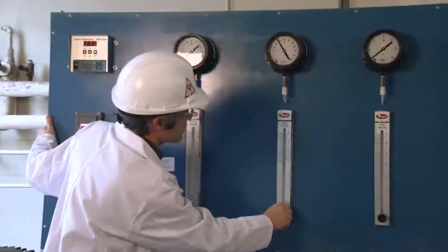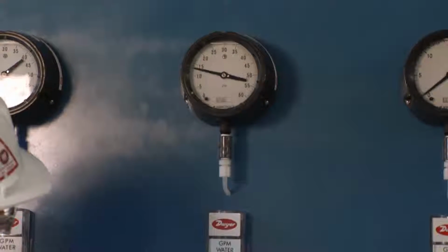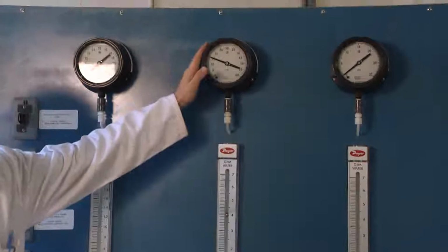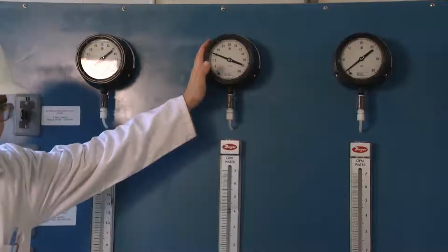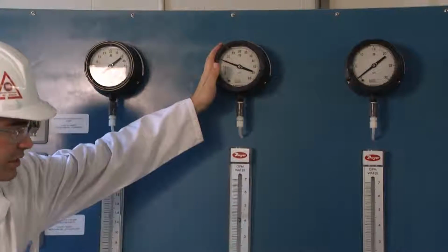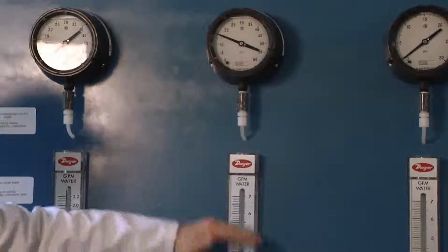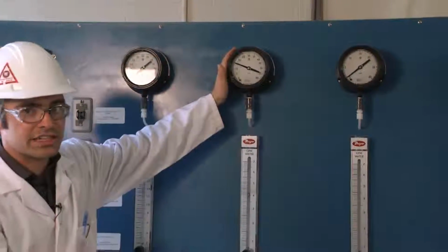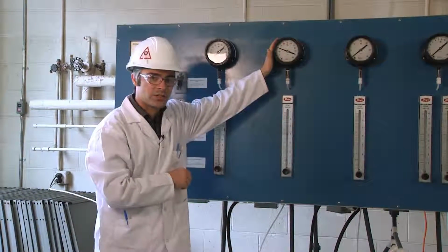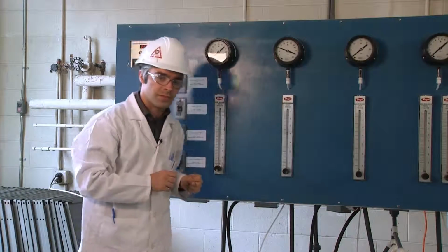As we attempt to increase or decrease the flow, you will see the pressure change accordingly. Keep note that for the first two pumps, you restrict the flow using the rotameter, and you'll look at the associated pressure difference within the apparatus. This will give you a clue into characterizing the pump and deciding applications that this pump is good for.